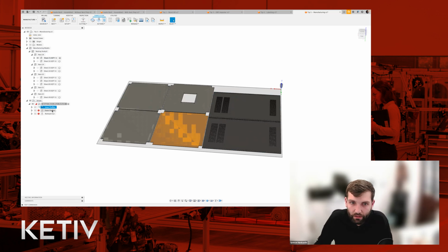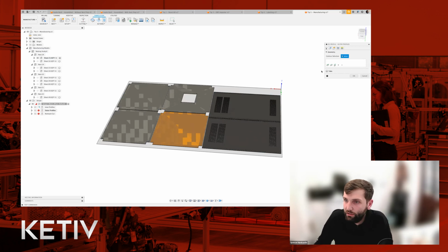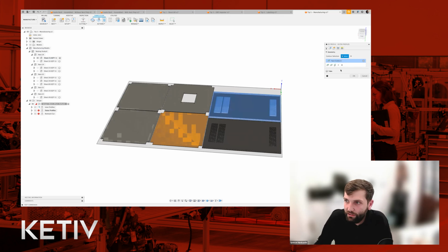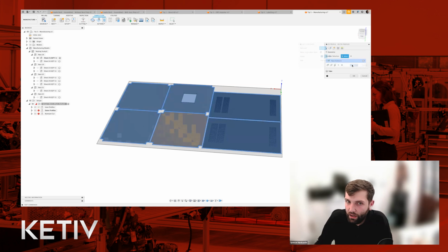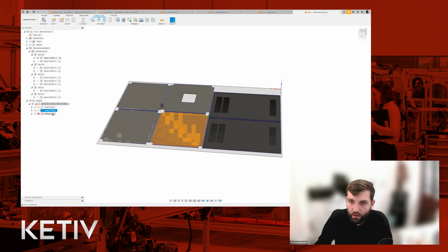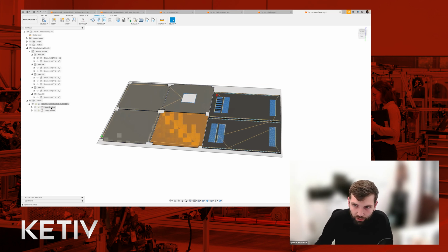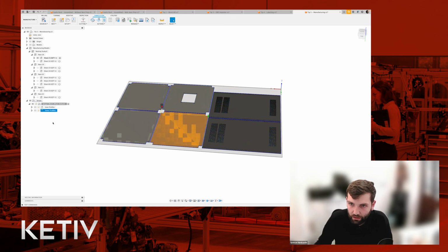From there, it's the turn of the outer profiles. So again, let's select our face, press the little cog, select same plane faces. This time it's only the outer, so that's the 2nd icon, and press OK. And last but not least, the remnant cut. There's no remnant cut on this file, so we don't need that one, so we can simply delete it. So at this point, what we've done is there's the internals and there's the externals.